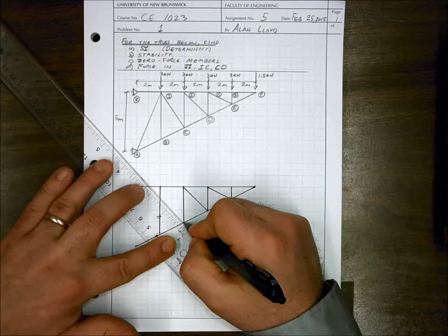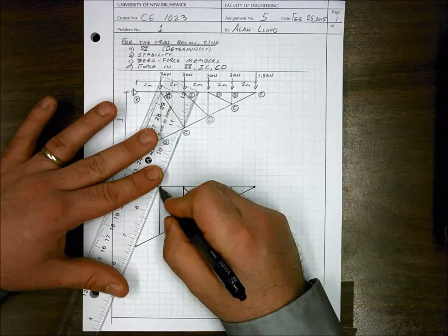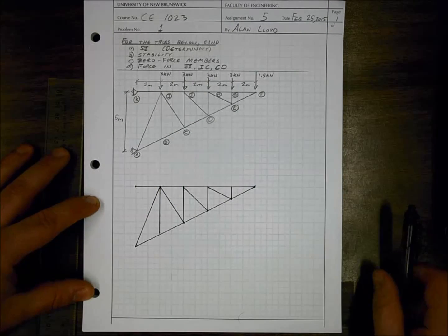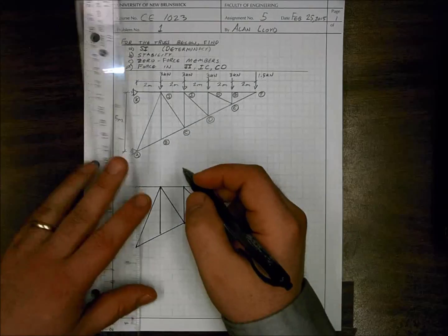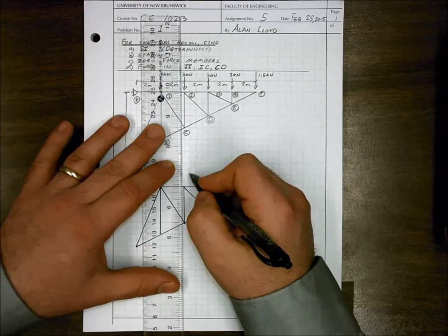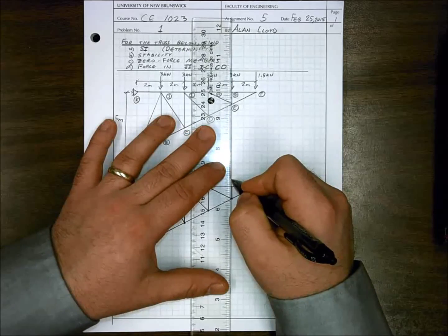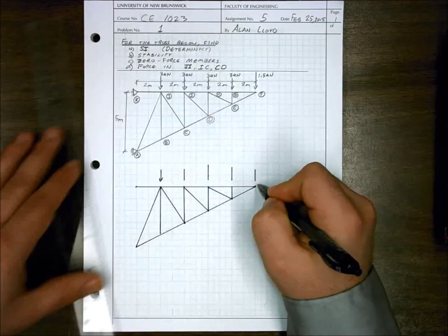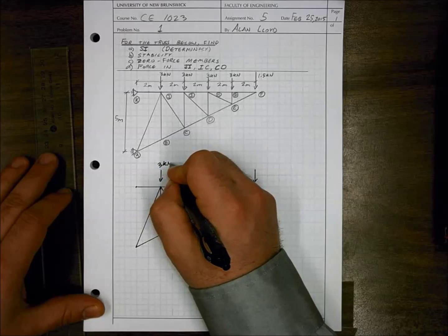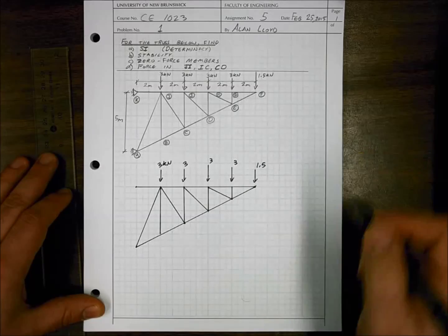But even if you have a problem where drawing the free body diagram seems kind of strange because we could just go ahead and add our support reactions to A and K there, the free body diagram gives us a little bit of a surety that we fully understand the problem. Just going through the exercise of drawing it, we see where all our forces are located, and we see what our entire geometry of the truss is. So it's really a valuable exercise, even if you think it's not really that useful in the final problem solving. The more complicated these trusses become, or any problem, the more important a free body diagram is.